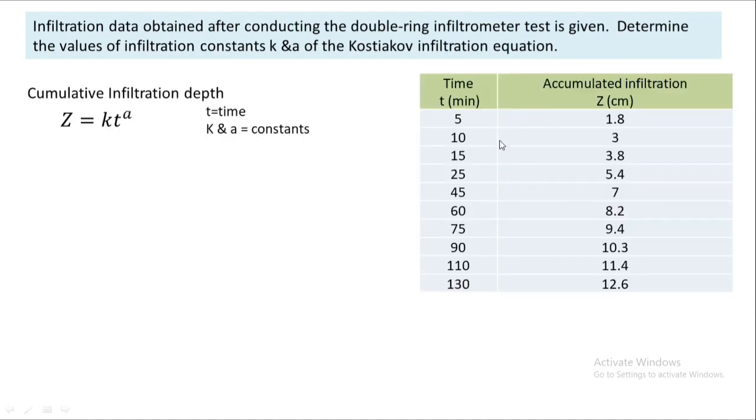At 5 minutes, the accumulated infiltration was 1.8 centimeters, and at 130 minutes, the accumulated infiltration was 12.6 centimeters. Now, using this data, we will obtain K and A.